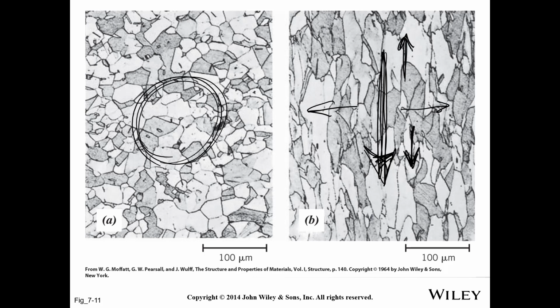So it's not isotropic anymore. And that's one thing that is critical, especially for some of you mechanical engineers, to take away from this class: real materials are often not isotropic, and you've got to be careful about that, because a lot of times in your calculations and designs you might assume that, but it's not true, especially when we start processing metals.